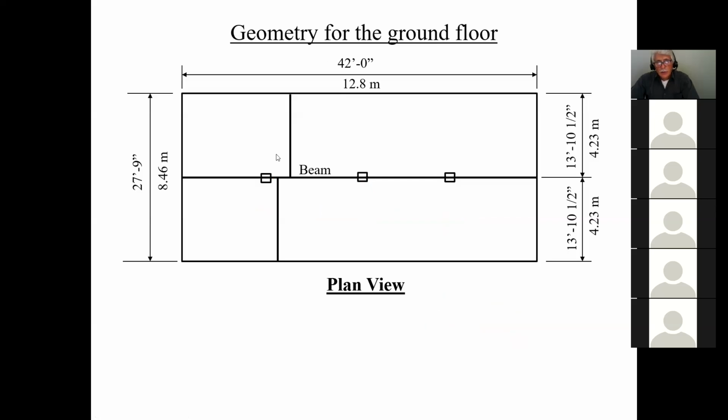So like I said, I like to keep 12 feet as the limit, same thing as for my solid wood joist. I don't like to go over 16 feet; I always limit myself to 16 feet for that. And when it comes to built-up beams, I like to keep 12 feet as the limit of my span. If I have to go more than 12 feet, well, then I'll see what the consequences are, how many plies I would need to get that bigger span.